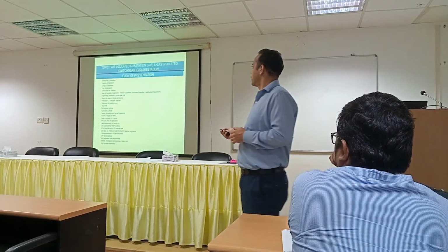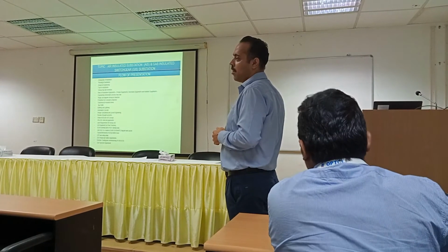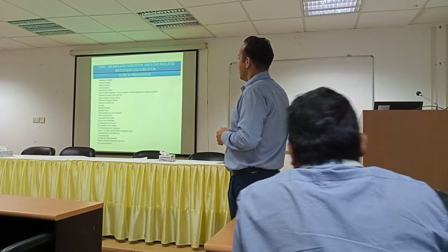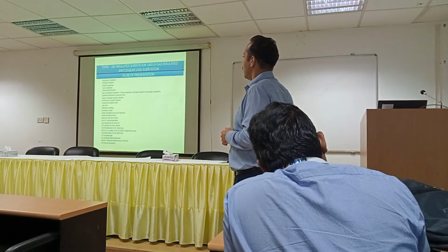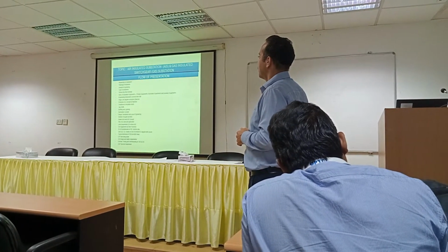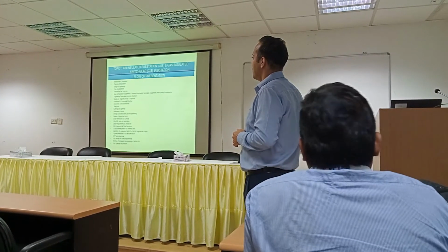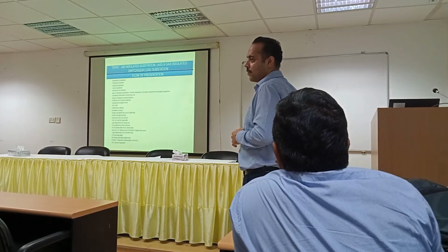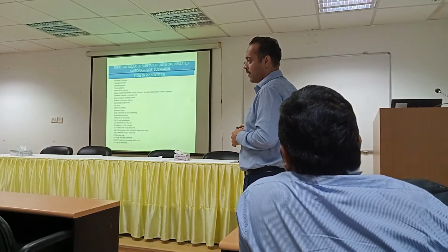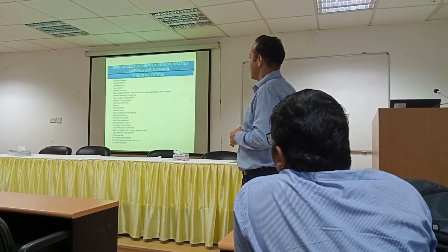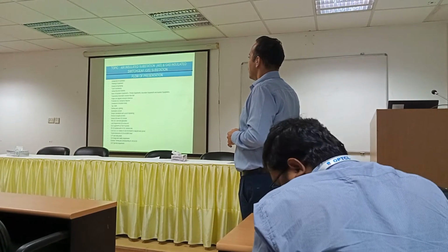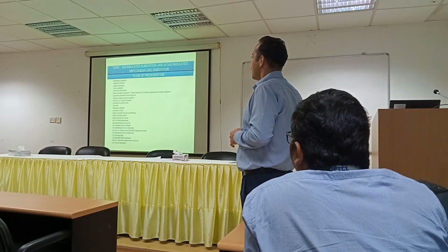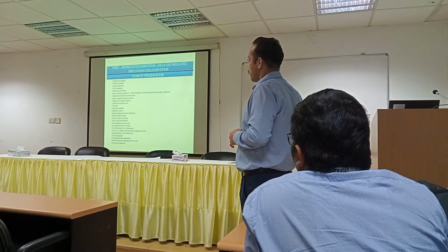First, the introduction. Then planning of the substation, how we will do the planning. Design and engineering, what elements are involved in design and engineering. How many types of substations there will be. Various busbar schemes, what is applicable for 132 kV, 220 kV, 400 kV, 765 kV, depending upon their feasibility and reliability. Other basics of substation equipment: primary equipment, secondary equipment and auxiliary equipment.